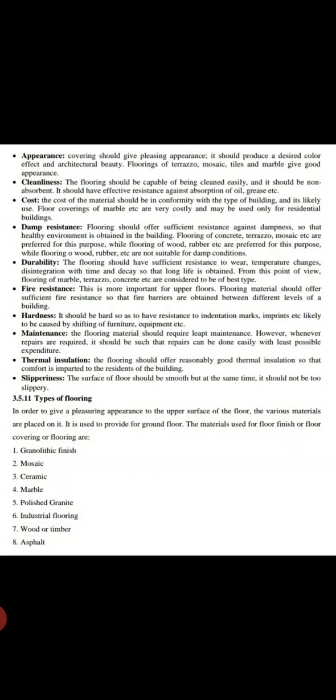Damp resistance. Flooring should offer sufficient resistance against dampness so that a healthy environment is obtained in the building. Flooring of concrete, terrazzo, mosaic etc. are preferred for the purpose, while flooring of wood, rubber etc. are not suitable for damp conditions.